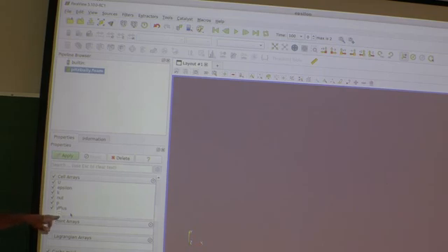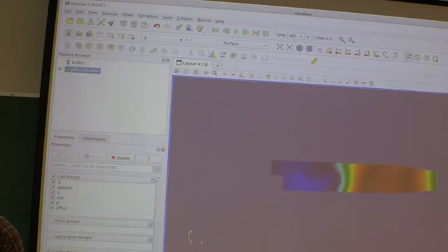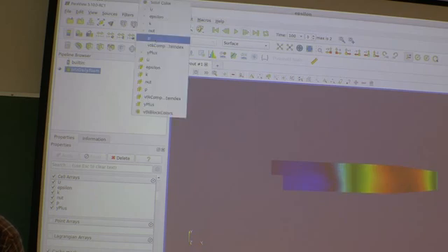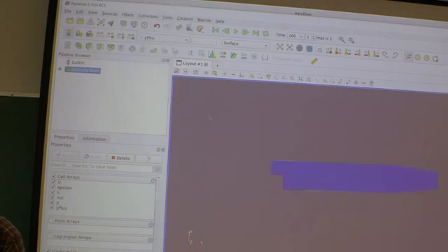You don't have omega because we don't use the K-omega turbulence model. So it should detect it automatically. If something is not checked, then check it and then click apply. So now we take a look at the latest time and look at y plus.